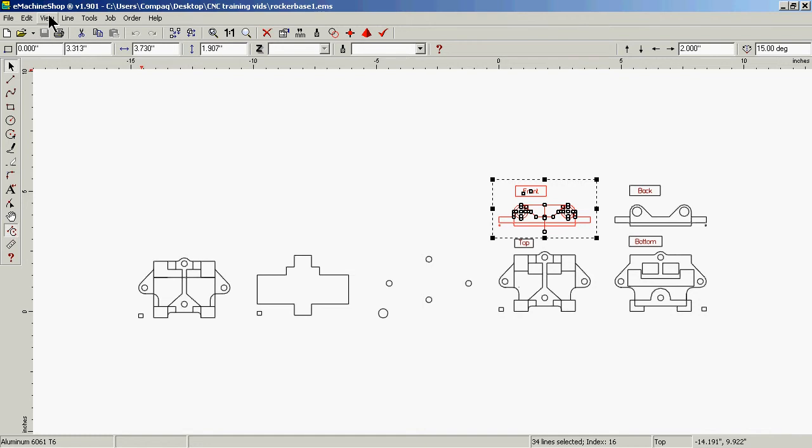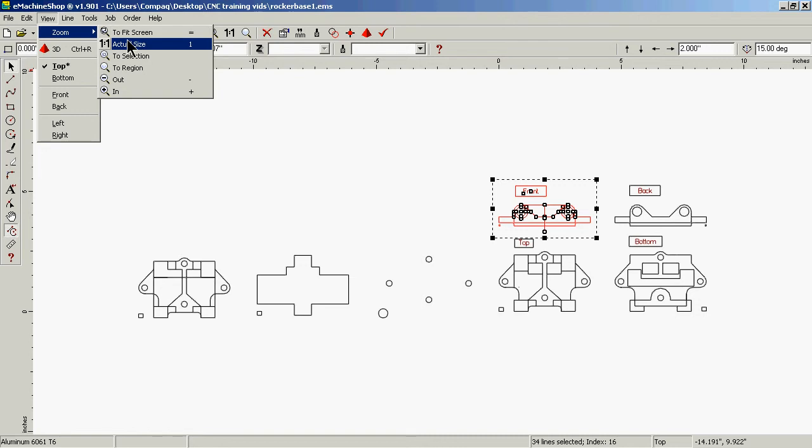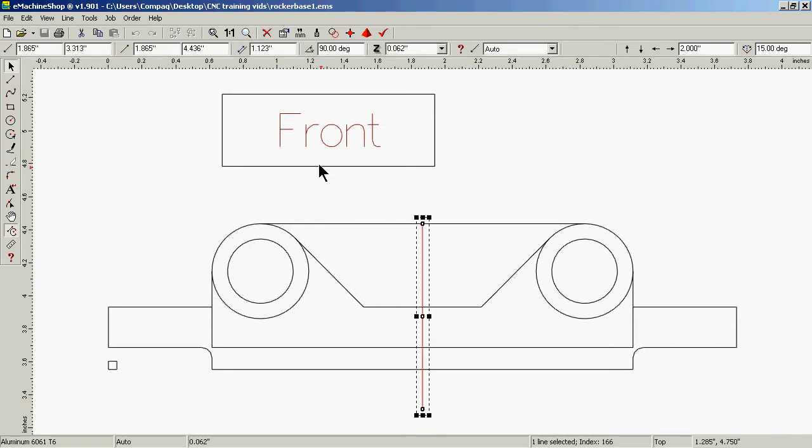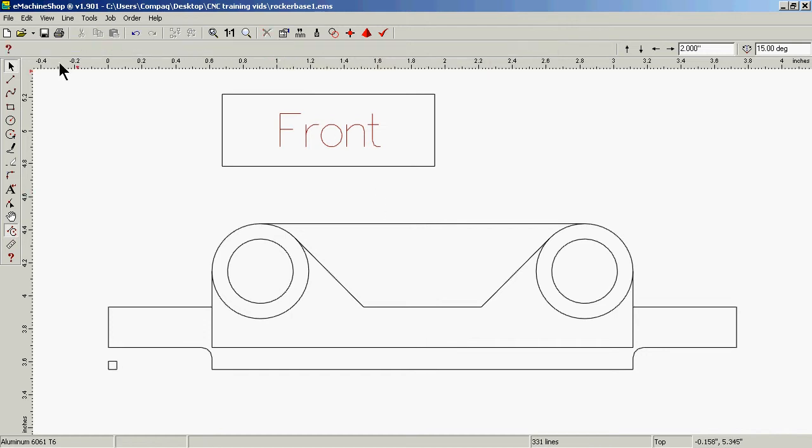Let me zoom to this area here and I'll show you where the problem started. Some of you might have caught this. I didn't. I looked at the measurement instead of the line. Zoom to the selection. If you notice here, this line starts way at the bottom, and I watched the video and I actually tried to snap it to this, but I didn't zoom in to do it, which I should have. And I ended up slipping off of it, and I snapped this line at the bottom, and I used that measurement of 1.123, and it's wrong. Let me go ahead and delete this off.